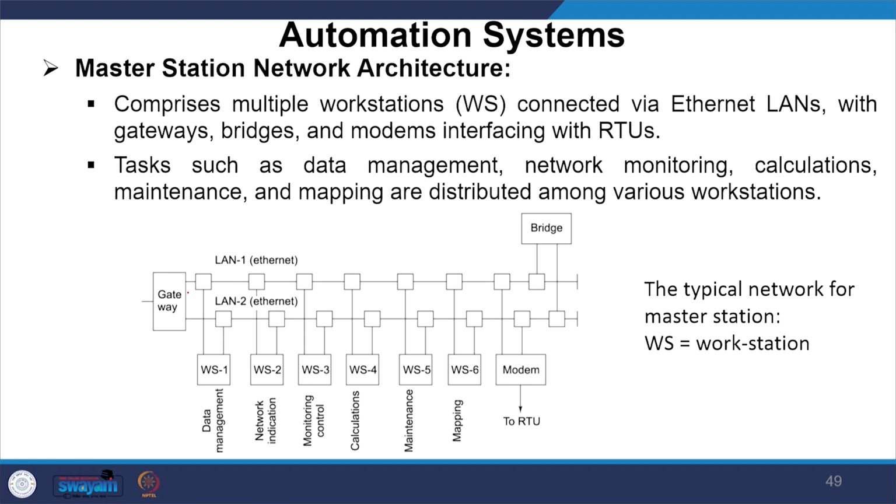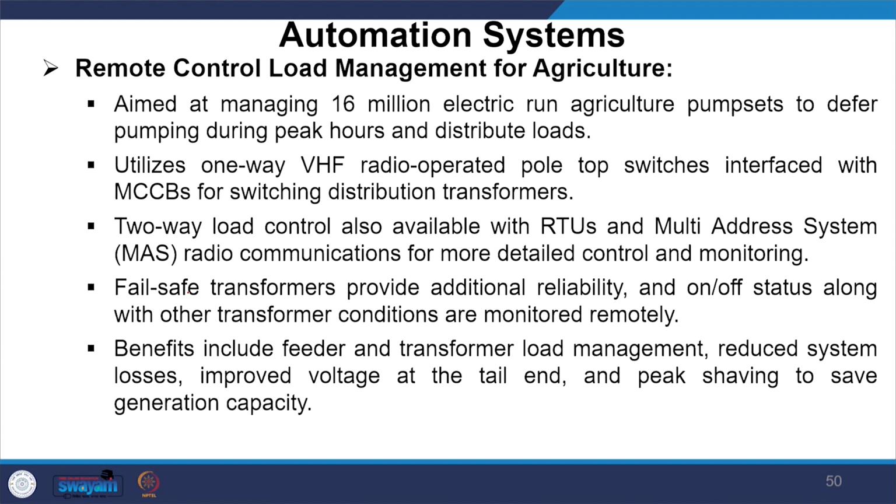So this is how you can see the master station network architecture, the typical network for a master station, which comprises multiple workstations connected with Ethernet LAN, with gateways, bridges, and modem interfacing with RTUs. Tasks such as data management, network monitoring calculations, maintenance, and mappings are distributed among various workstations. Remote control load management for different applications, including agriculture.